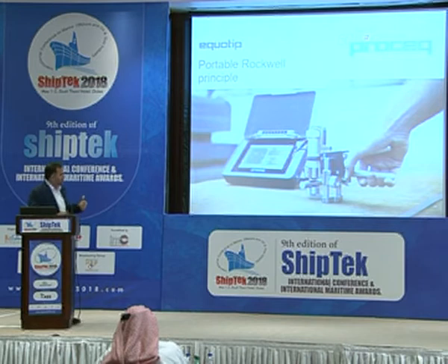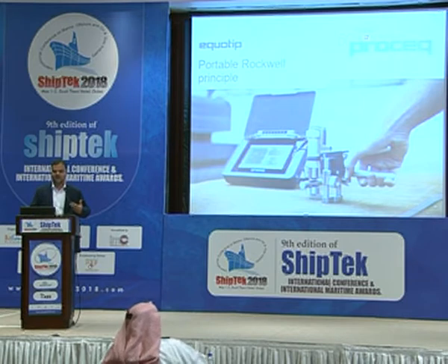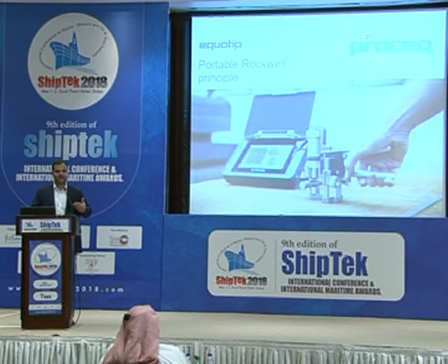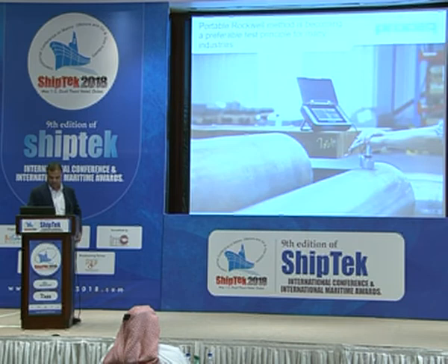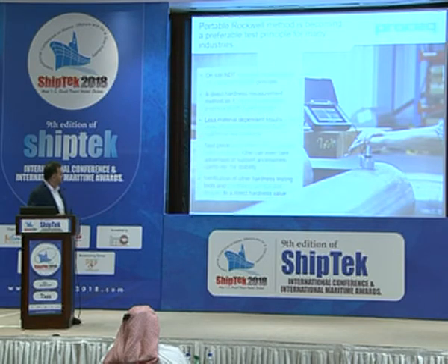And the other commonly known technique is the portable Rockwell. We all know in the industry the Rockwell hardness, which is the basis of hardness measurement basically. So now the same benchtop hardness measuring, the Rockwell indentation type method, has been reduced to low load and portable, which has also become a non-destructive tester because the indentation is a micro indentation type. So basically it has a diamond indenter, and the method is becoming a preferred test principle for many industries. Over here we can see some of the applications.